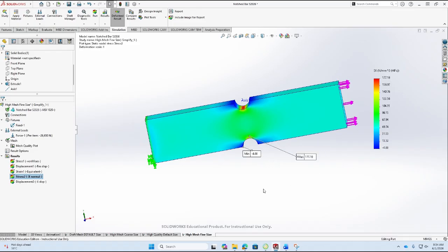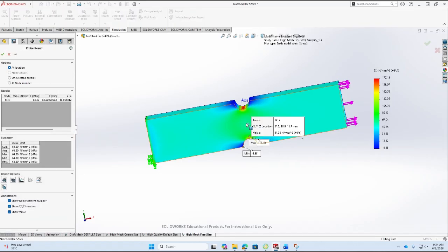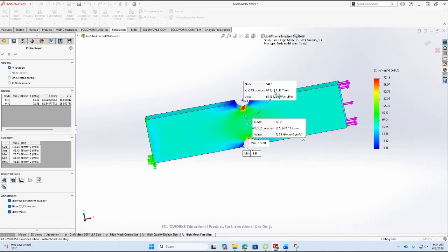But before, I just forgot to mention one point in the start. You see, we also calculated the net stress value from our hand calculation. But if you probe in this region, you are not going to find one unique number over here. Okay, so for example, here it's like 64, here it's like 72. So that net stress value is never actually present in the model, because in reality the stress concentration profile makes it different in different locations.